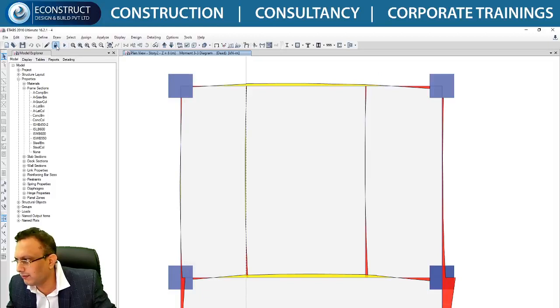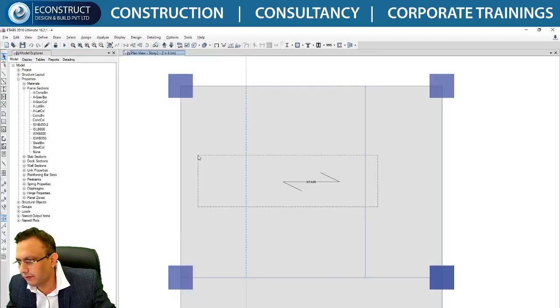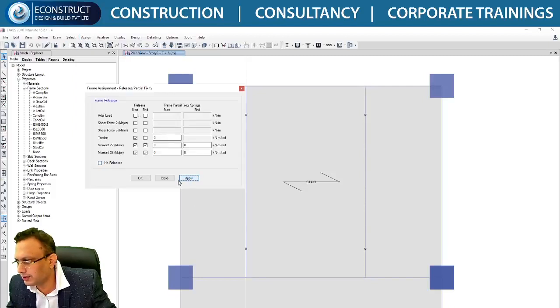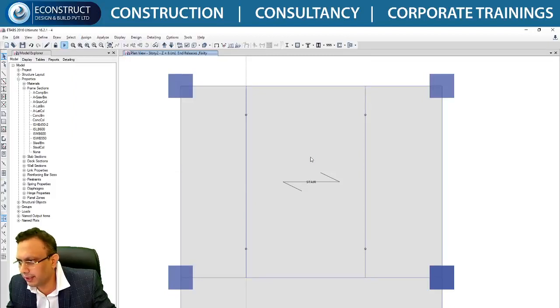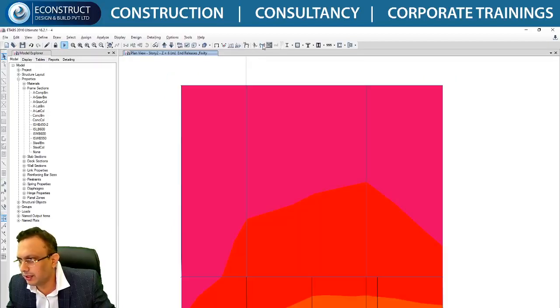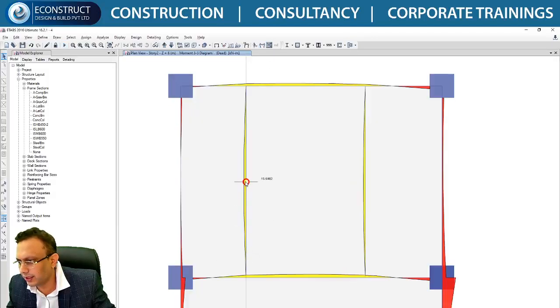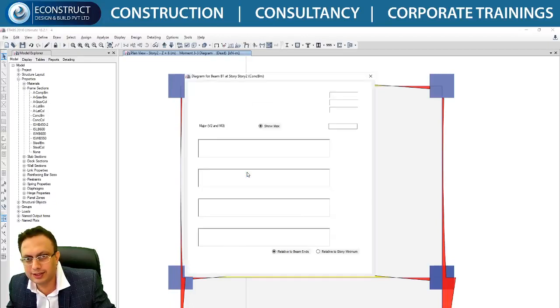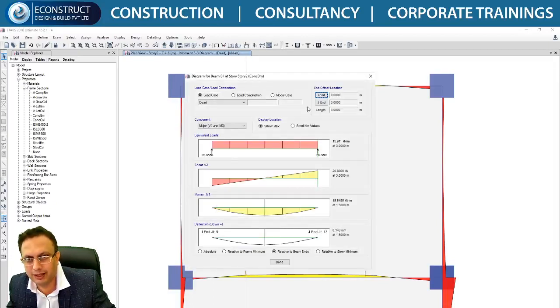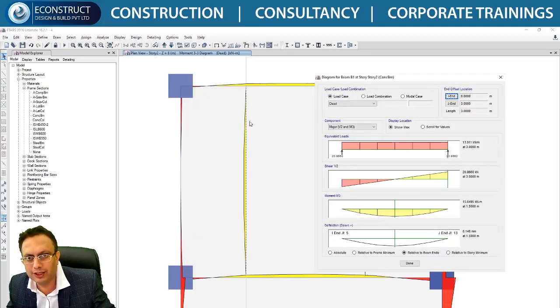So what we do is we unlock the model and give these two beams as released. This is the before and after, the pre-release and post-release information. 13 and 6 was the bending moment. Now after releasing, what are you getting? See here. The 13 has become 15. Am I right? This is the bending moment that you want for this beam. So the 6 kilonewton meter bending moment has become 16, which is huge. Whereas at this place it is 0, which is expected. At this edge it is 0, and at this edge it is 0.